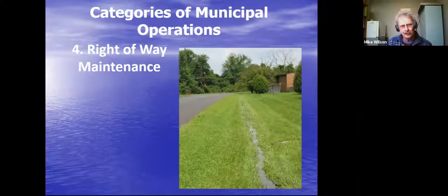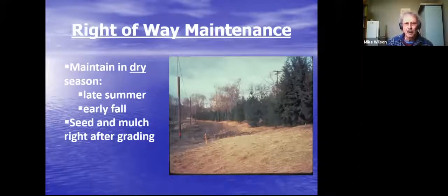Another required category is right-of-way maintenance. You want to maintain your right-of-way maintenance areas during a dry season. Late summer, early fall is perfect. And if you do any grading or change of that grade or disturb any of those areas, you want to seed and mulch right away.